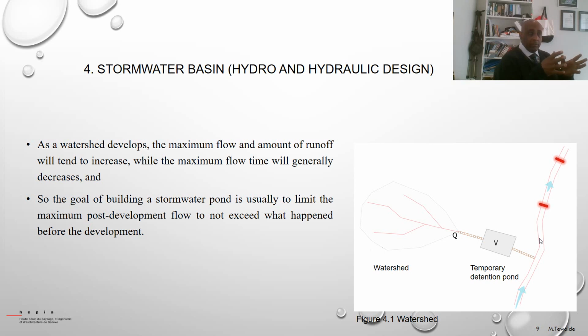Most of the time, the purpose of the detention basin is to reduce the peak discharge. If it is concrete or something like that, an impermeable surface, then the volume might not be decreased as much as the peak discharge decreases. That is the purpose of the design of a stormwater basin.